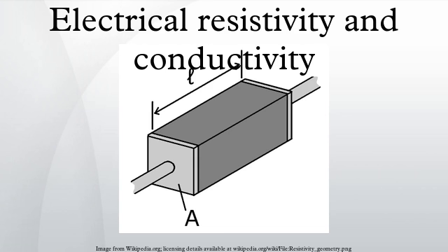The reason resistivity is defined this way is that it makes resistivity an intrinsic property, unlike resistance. All copper wires, irrespective of their shape and size, have approximately the same resistivity, but a long, thin copper wire has a much larger resistance than a thick, short copper wire. Every material has its own characteristic resistivity. For example, rubber's resistivity is far larger than copper's.